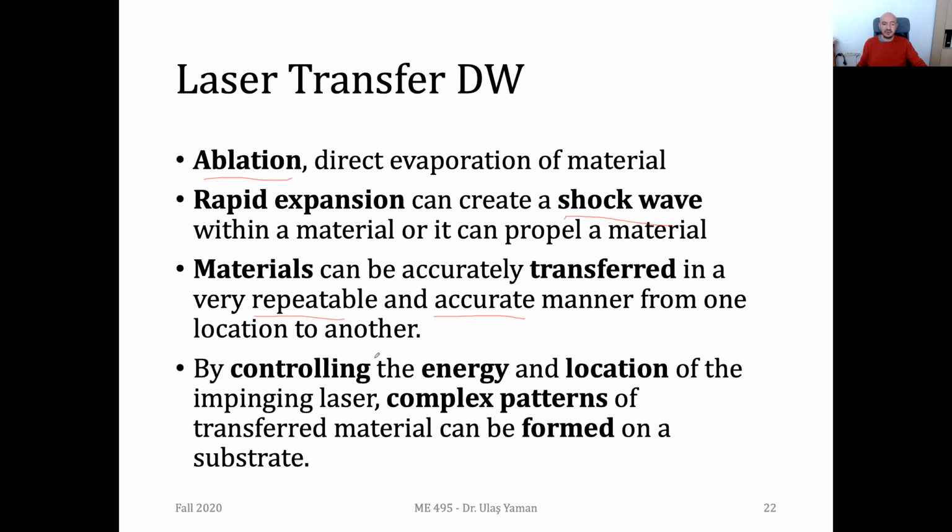And obviously, since it's a printing operation, you need to control the location of your laser or the location of your material. So we need to have control on the XY plane or XZ plane. It depends on your orientation, but we need proper motion control in 2 axes.